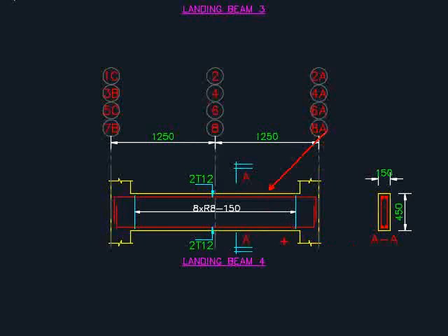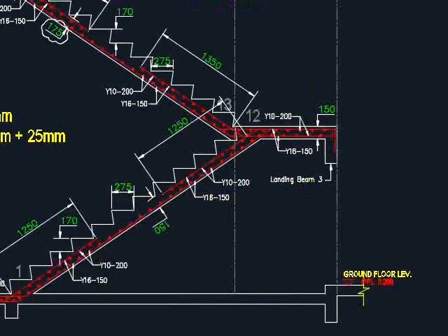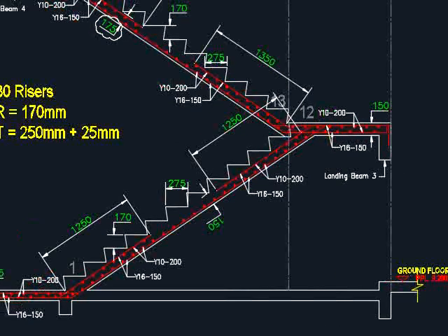There will be the main reinforcement bar as well as the shear links, and to indicate the existence of the columns or stiffeners. The landing beam is very important as it will govern the load resisting mechanism of the staircase, whether it is simply supported or going to be cantilevered.